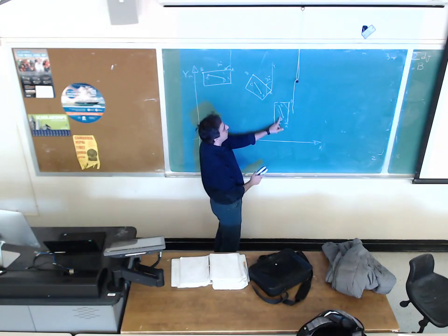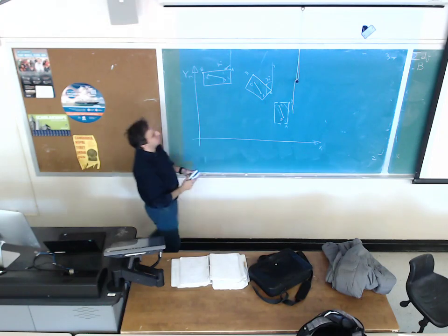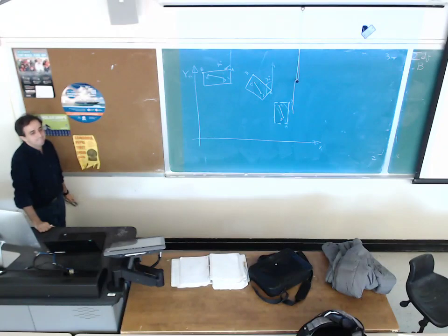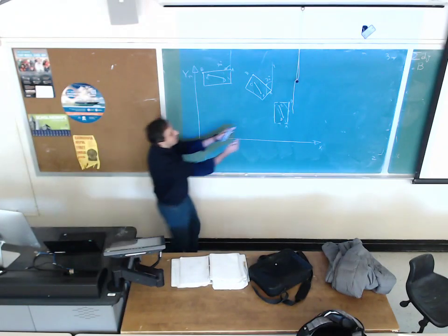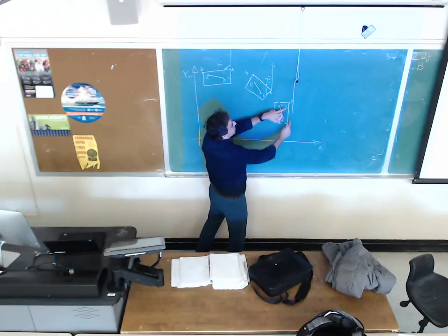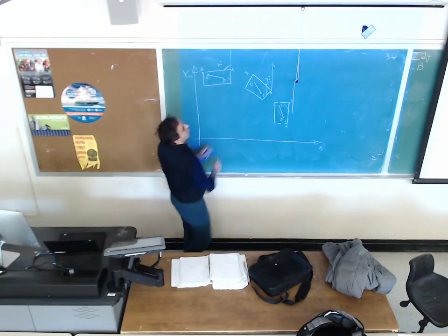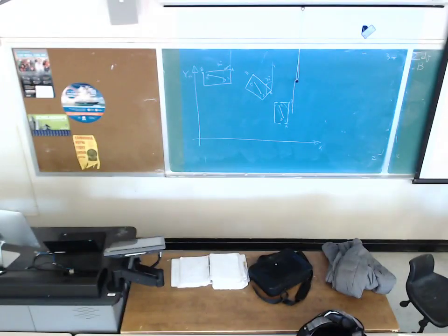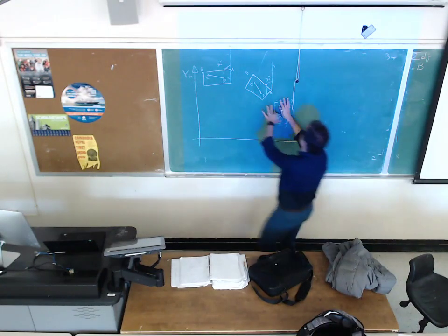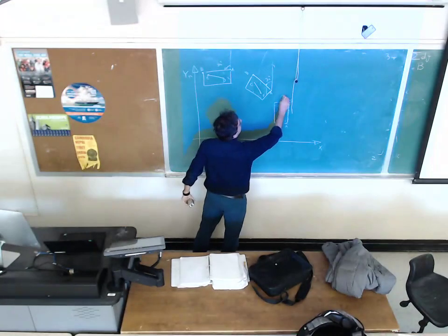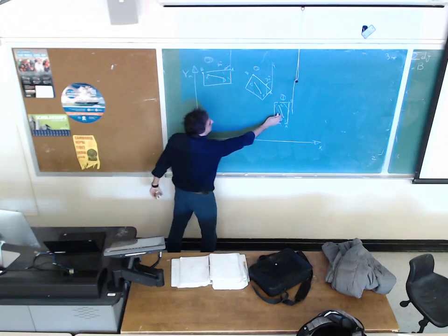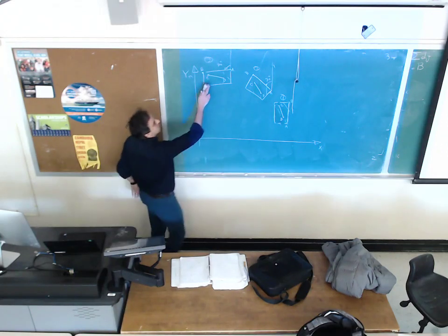What would be the rotation of this line from this position to this position? And from this position to third position? Same as, exactly the same as if you just track one line of the rigid body over the 3 precision points, the other lines are gonna rotate at the same angles. So I can say that the entire rigid body from first precision point to the second precision point has been rotated by 30 degrees, and from the first precision point to the third precision point has been rotated by 90 degrees.